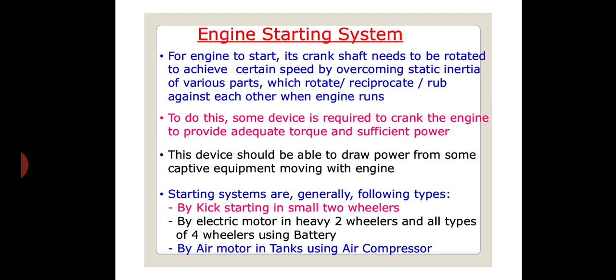This device should be able to draw power from some captive equipment moving with the engine. Starting systems are generally by kick starting in small two-wheelers, by electric motor in heavy two-wheelers and also four-wheelers, and by air motor in tanks using an air compressor.